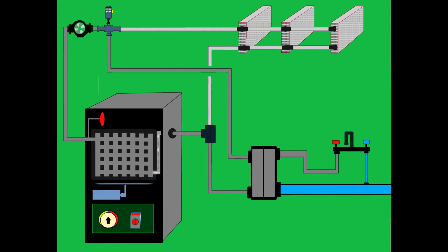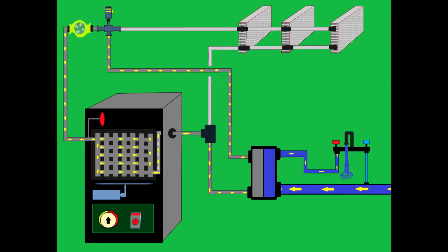I will show you more in detail how these things work, but as I said, all systems have pros and cons. So if you remember, at one point I said that when you open the hot water, then you'll see the pump is activated and the boiler is preparing to run. Now guys, you really have to understand that this process should happen very fast. This is an instant heating boiler, and you don't want to wait 5 hours near the tap until the water gets very hot.